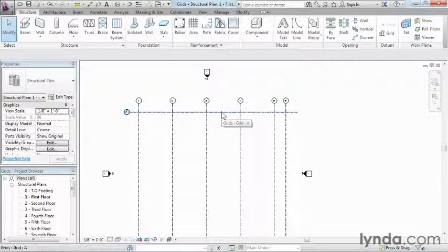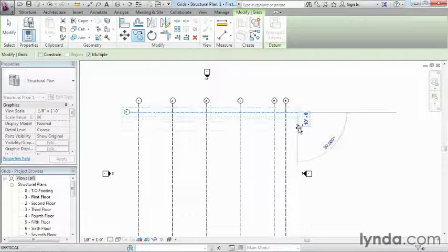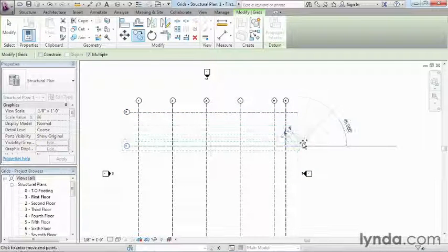Now, with the letter A here, we could continue to draw the way that we have been doing, but I'll point out that you can also use another command, the copy command, in order to be able to do this. So go ahead and select on the level, click on copy, move straight down, and when you see those temporary dimensions showing up there on the side, in this case it says 13 feet, go ahead and just type in 25. And it'll continue this 25-foot spacing.